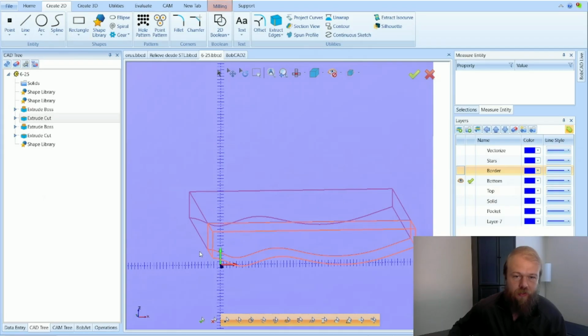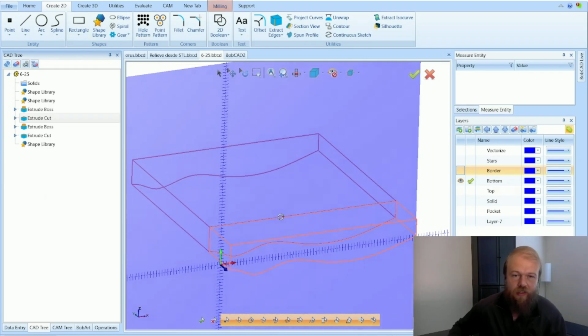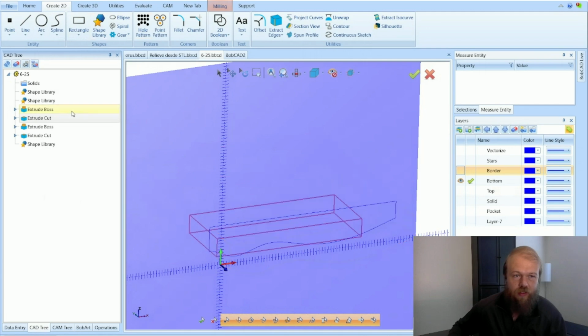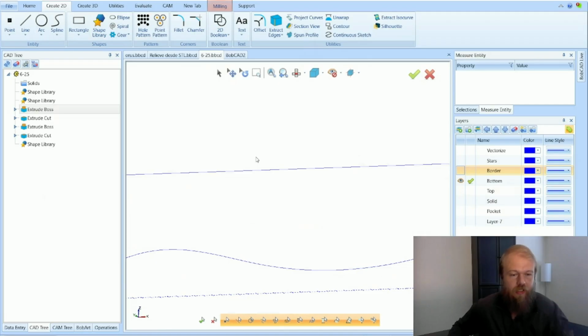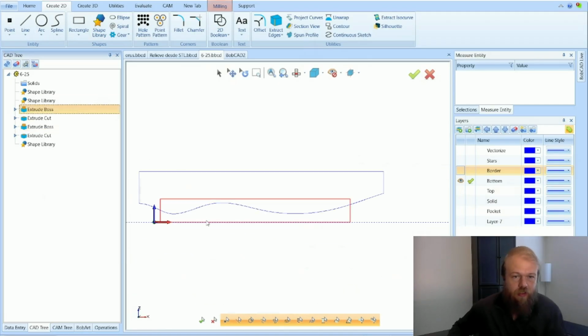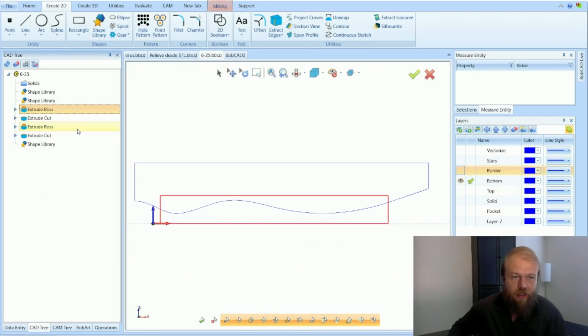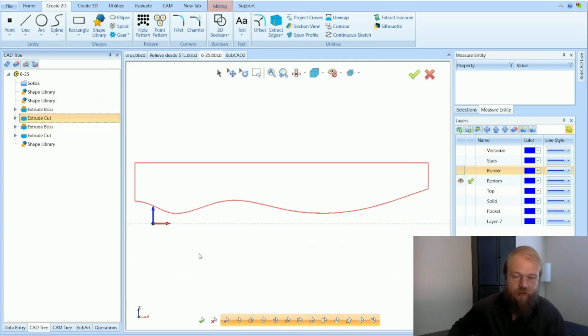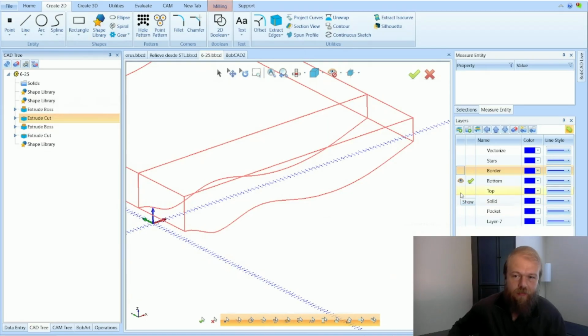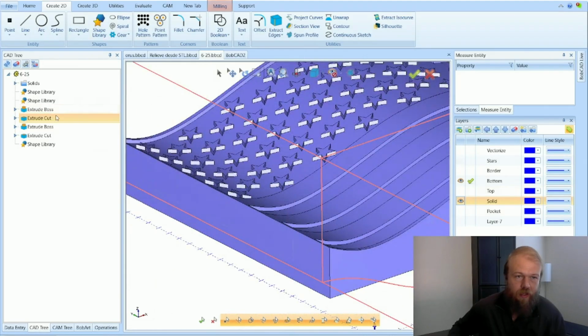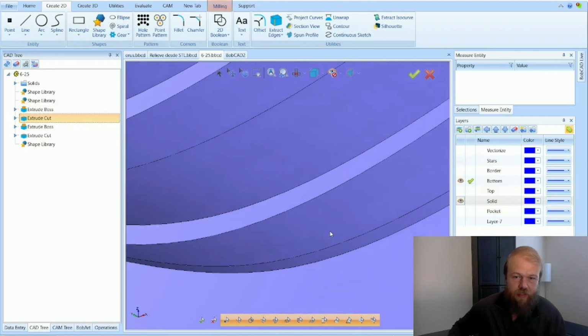I made a couple of vertical lines, and then from the 2 endpoints at the end, I made a line going horizontal across to sort of make this block shape so that I could cut this block out of my original extrude boss here. So if I look at it from a front view, here's my original extrude boss. Here's my extrude cut that I'm cutting away from. Then I'm adding more to my solid here, because my original extrude cut down to here.